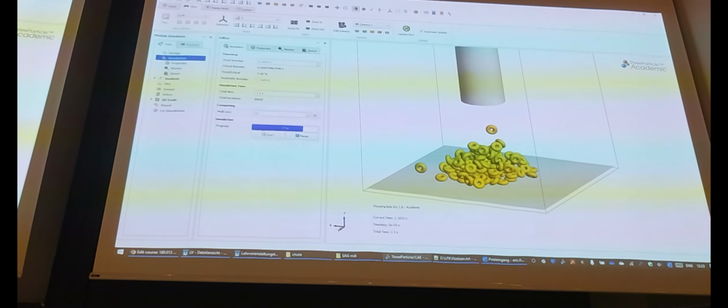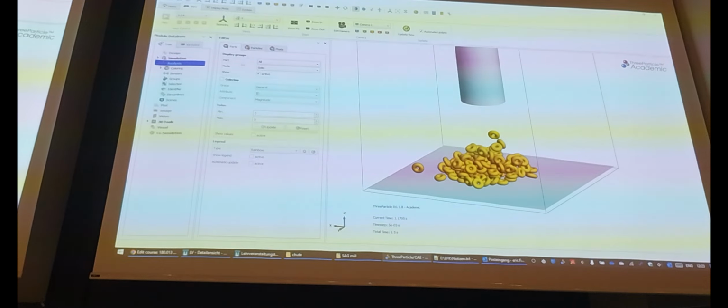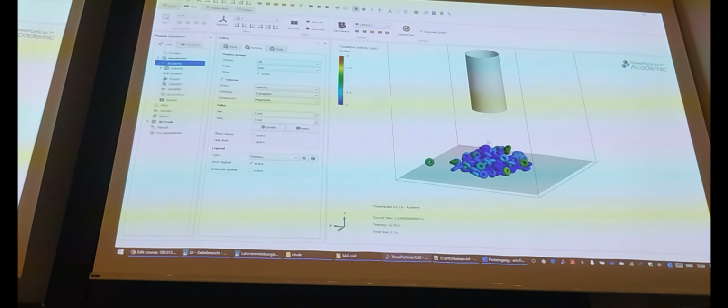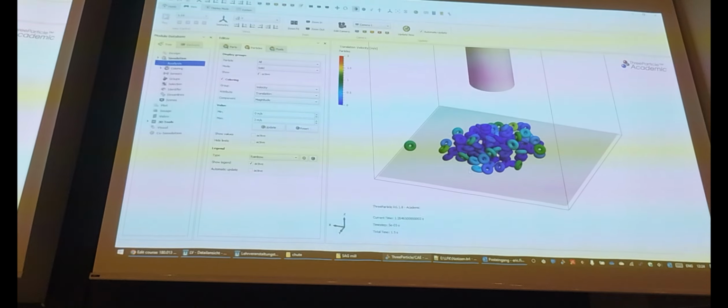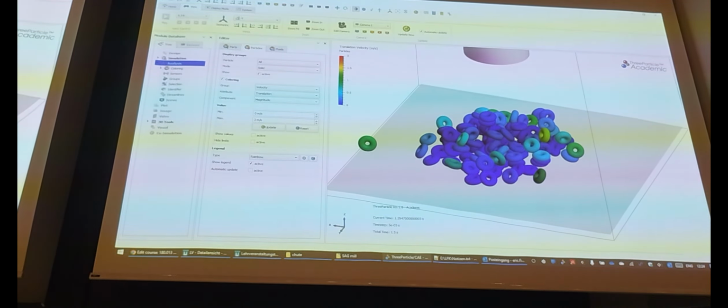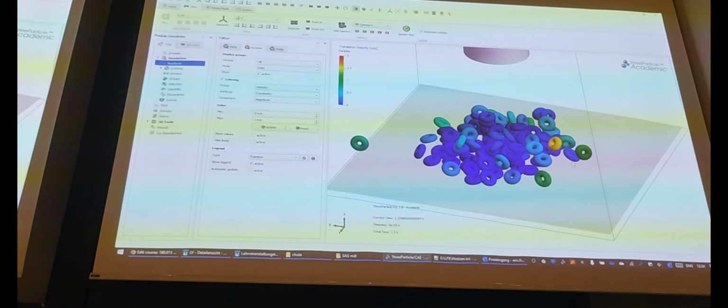And the question could be, how long should we simulate? A good indicator would be, you can do an analysis during your simulation for the particles regarding velocity, just as we did. Take a look, for example, between 0 and 2 seconds, and see if most of the particles settle. For example, that donut seems to roll away. If the particles settle and there are not that many colorful donuts, more or less all blue, then you're probably good to stop the simulation.